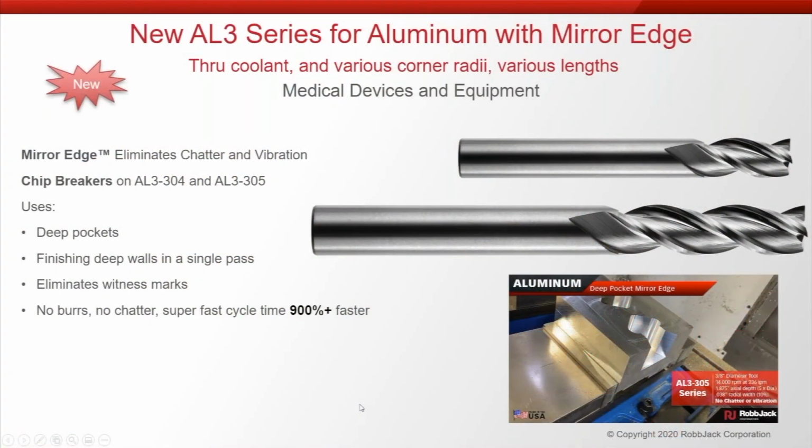So if you have an application where you're cutting aluminum and you're running into vibration and chatter, that mirror edge is a magic bullet. It'll solve everything.